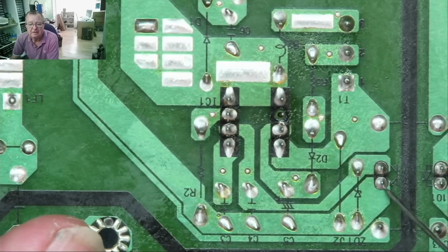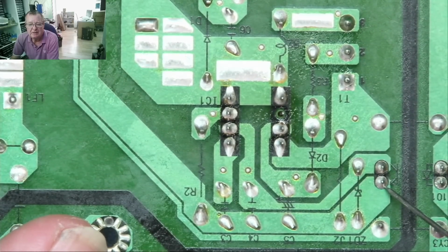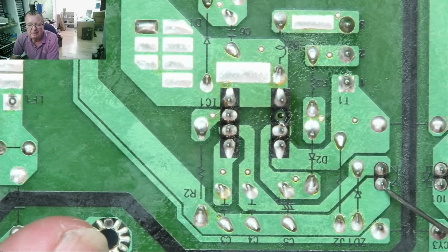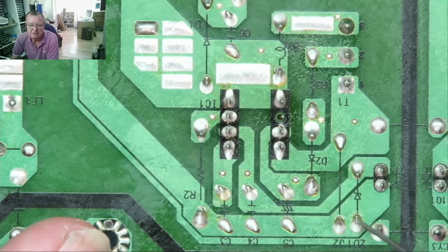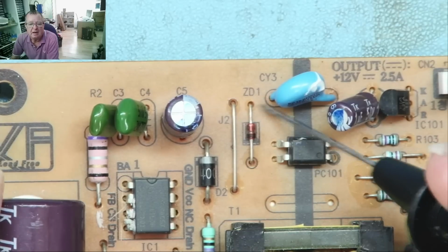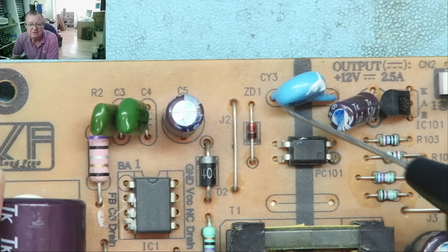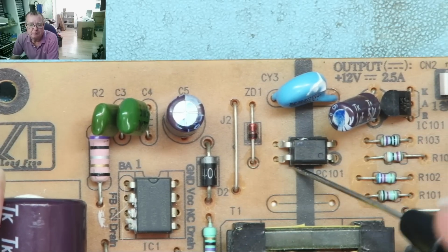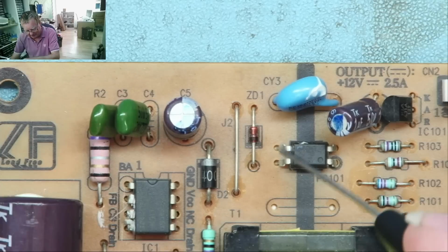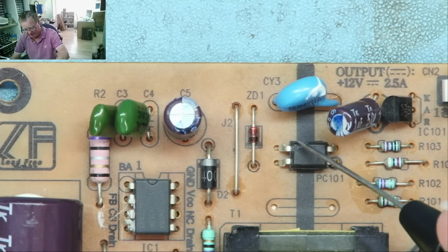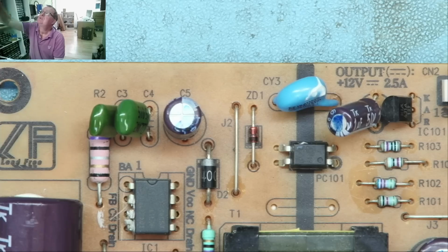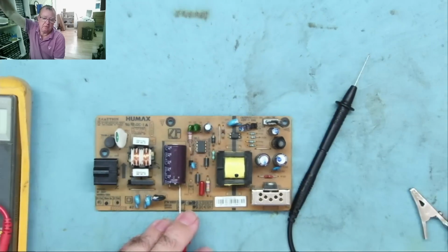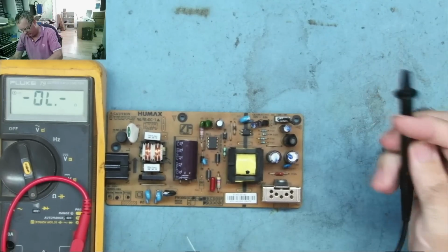So this end of the opto-isolator is ground, and the easiest way to clip our meter leads on, because we need at least 3 hands to do this otherwise, is probably just attach it to this diode. If you look on the other side, there's a diode there. This end is connecting to the negative end. This goes to the positive end of here. This is actually a Zener diode, and it's just to prevent high voltages appearing across the opto-isolator transistor. But it'll give us a good place to attach our meter.